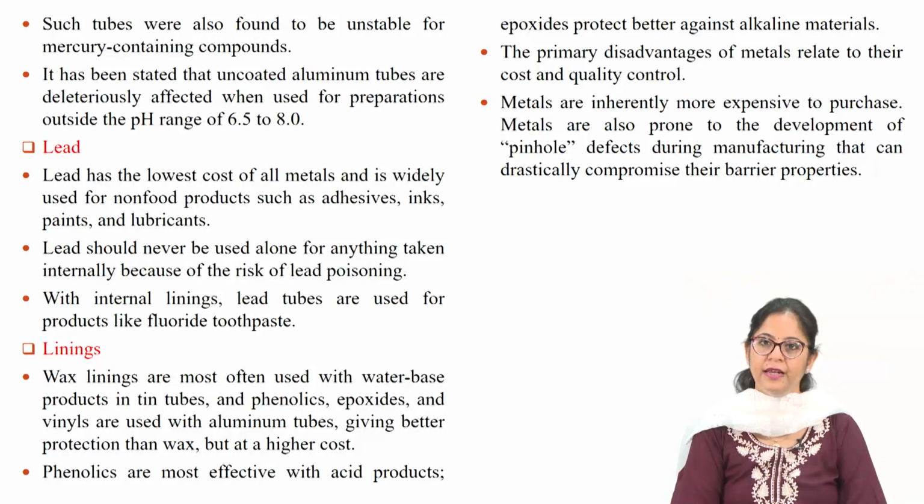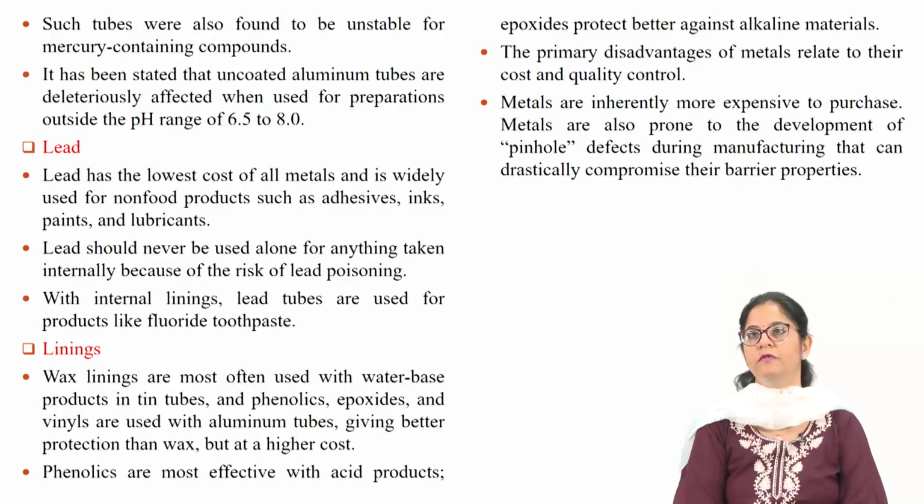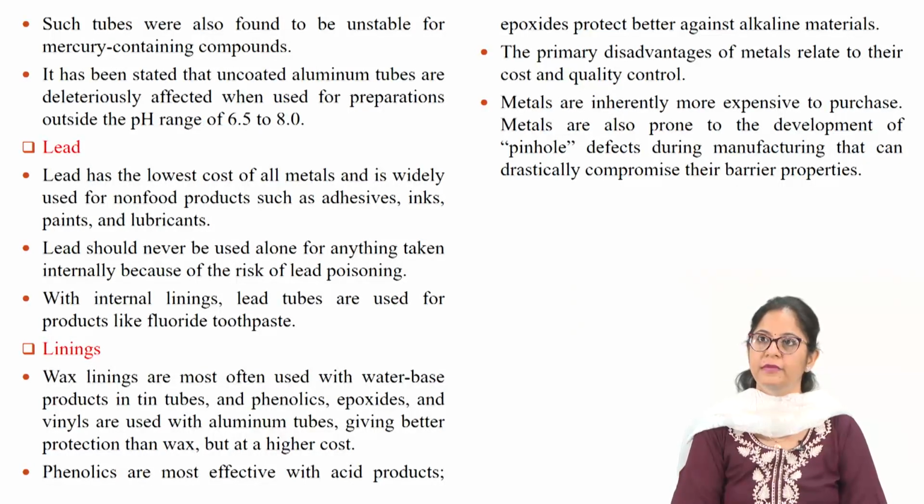Wax linings are most often used with water-based products in tin tubes, and phenolics, epoxides and vinyls are used with aluminium tubes, giving better protection than wax but at a higher cost. Phenolics are the most effective with acid products. Epoxides protect better against alkaline material.